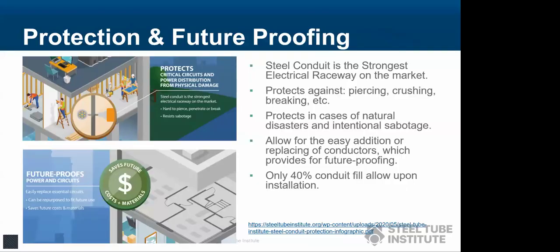Steel conduit is the strongest electrical raceway on the market. It protects against piercing, crushing, breaking, etc. It protects in cases of natural disasters and intentional sabotage, which is increasingly becoming a concern. It allows for the easy addition and replacement of conduits, which provides for future proofing.